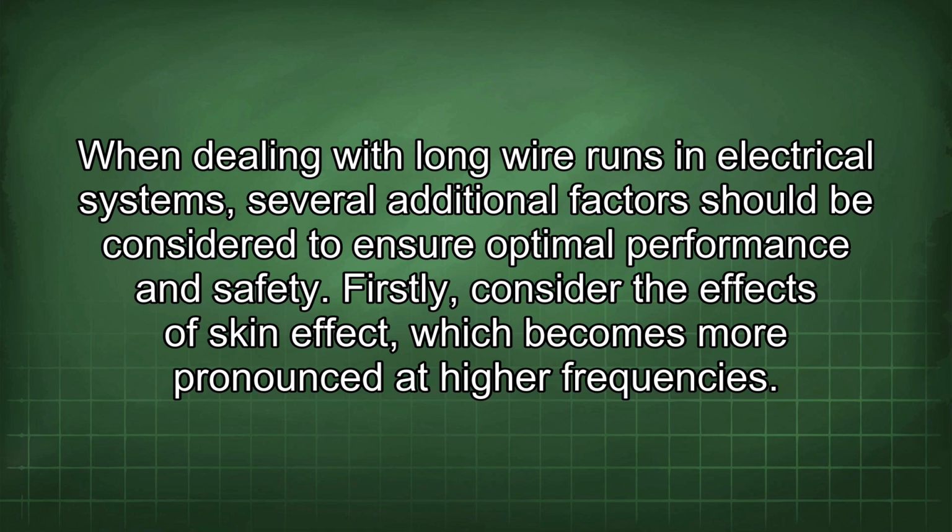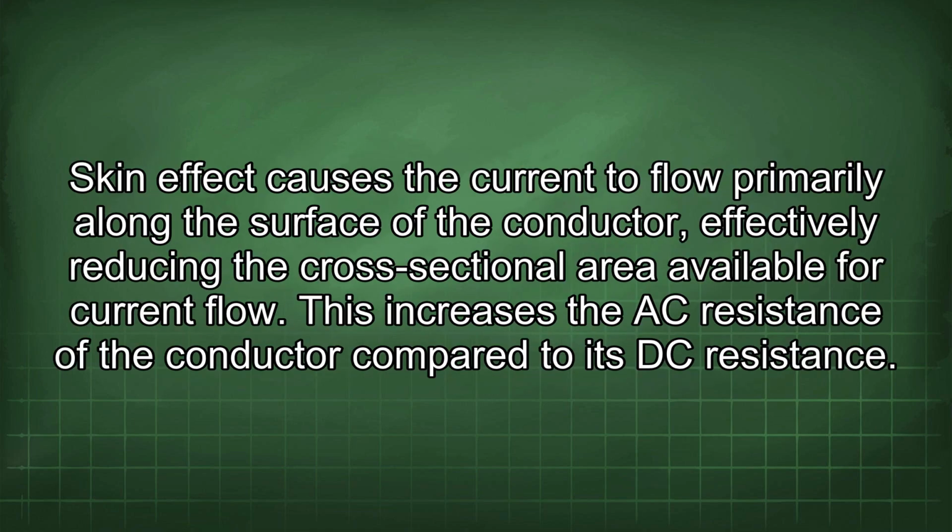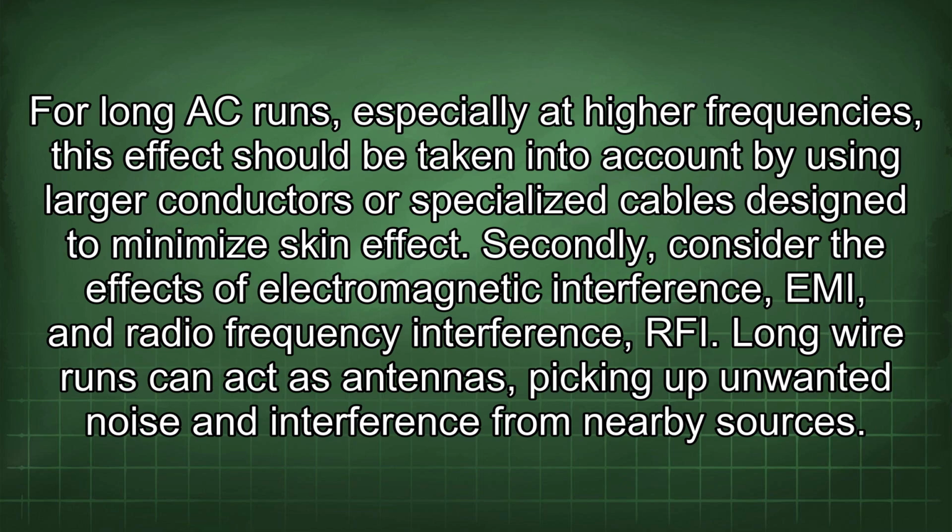Firstly, consider the effects of skin effect, which becomes more pronounced at higher frequencies. Skin effect causes the current to flow primarily along the surface of the conductor, effectively reducing the cross-sectional area available for current flow. This increases the AC resistance of the conductor compared to its DC resistance. For long AC runs, especially at higher frequencies, this effect should be taken into account by using larger conductors or specialized cables designed to minimize skin effect.